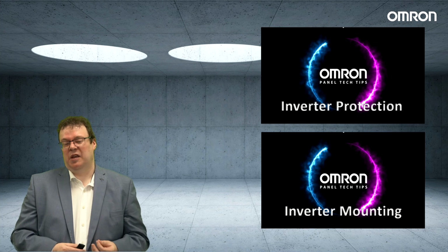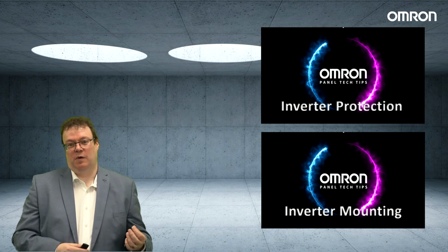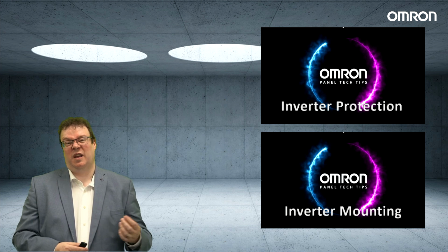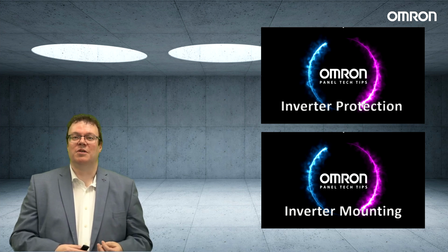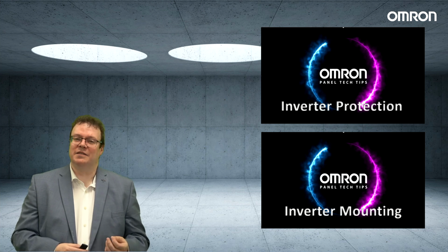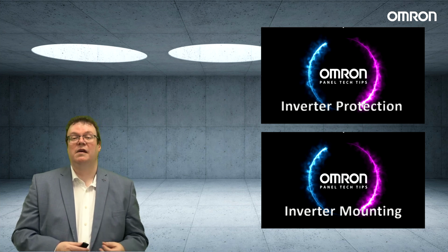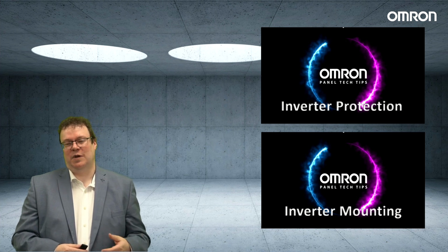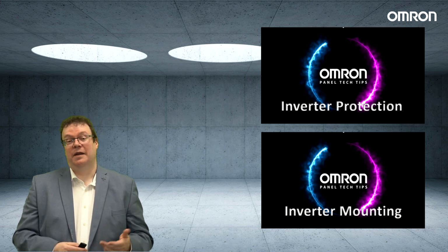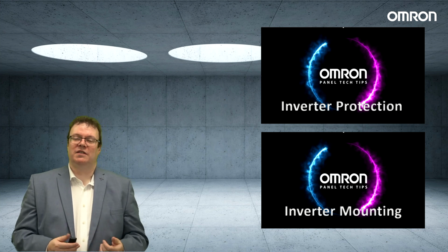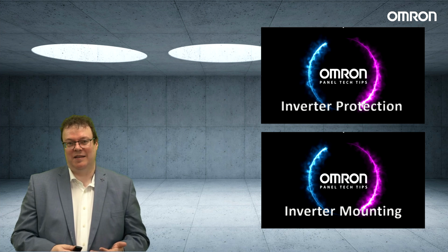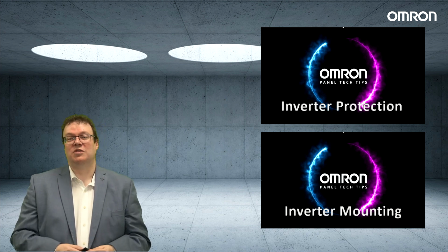One of the issues that can occur, of course, and when we looked at the CR network before, is that the high-frequency noise is jumping across the capacitor in the filter and going down to earth. This can cause issues in terms of tripping out things like RCDs that you may use for protection in the circuits. We'll discuss the way around this and the special type of protection that you have to use in our upcoming panel talk on inverter protection. Also another important factor is to look at how we actually mount the inverter in the panel itself and the cabling attached to it, where it's mounted and glanded, and we'll also discuss that in an upcoming talk.